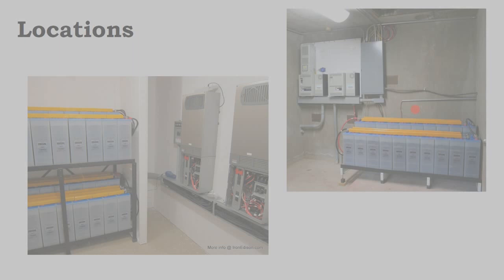And the inspector might come back and say, well, that may be the case, but metal conduit still can't be in a battery room. So what you need is a metal conduit with a PVC coating around it, like that flexible metal conduit. Depending on how tough your inspection is, what we can see here is it looks like they're going into a PVC bend at this point.